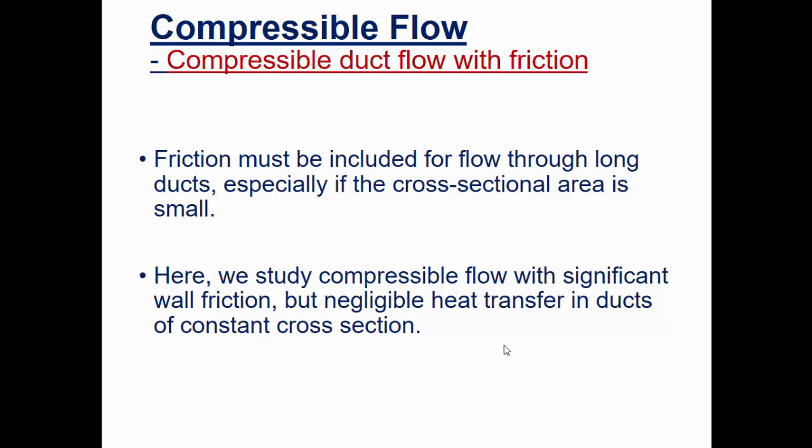For this topic we are going to look into the compressible flow with the external factor of friction, which is closely related to the wall friction of the channel. To simplify the discussion, we will neglect for now the heat transfer in the duct, and we are going to look into the analysis with a constant cross-sectional area throughout the flow.